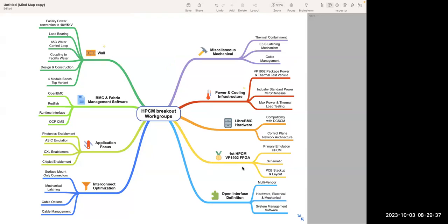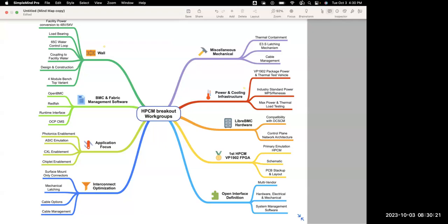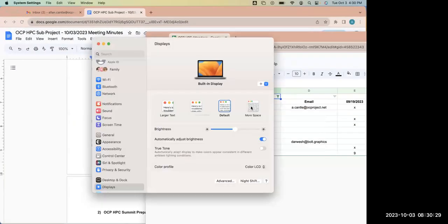The modules that suit our stack, and also, I just think Intel are quite a long way developed with CXL on their FPGA line. Therefore, it should give us an easy route to CXL 2.0 adoption. That's really the confluence of factors that make it make sense for us. It looks like Intel are going to be somewhere close with CXL 2 for Emerald Rapids, and the HBM variant, the Emerald Rapids Max, would offer us a form factor that would fit HPCM. And then if we combine that with the Agilex parts that also support CXL 2.0, then we may get somewhere close to being able to run CXL 2 sooner rather than later.